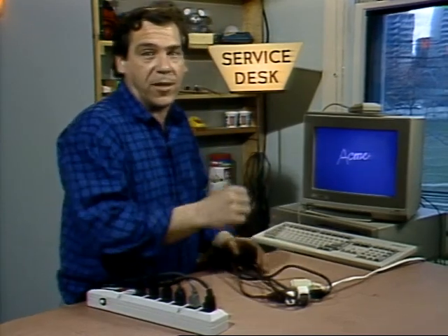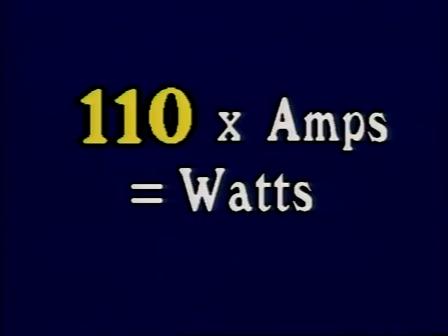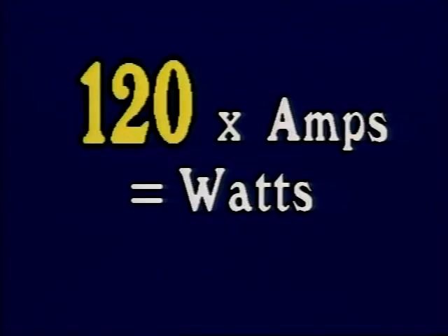Our modern electronic wonders are marked in watts. Now, regular Acme viewers are already cringing in fear of seeing this graphic again. Volts times amps equal watts. The wall socket voltage is fixed, or sort of fixed. My father called it 110. I grew up calling it 117, and the electric company will tell you it's 120. Who's counting? Ballpark it at 100. That makes the math simple and allows you to err on the side of safety.